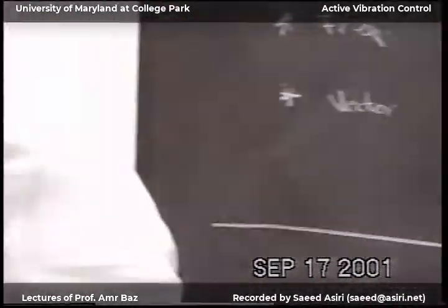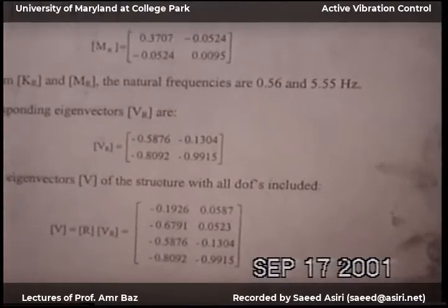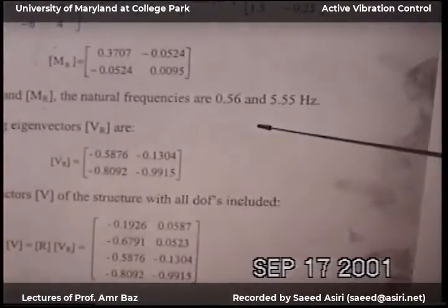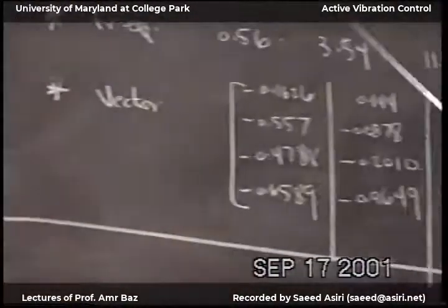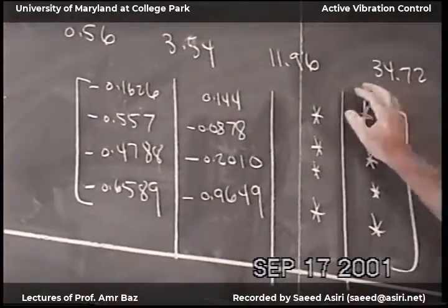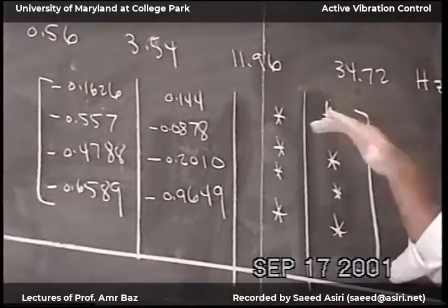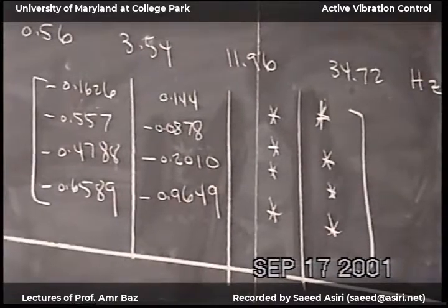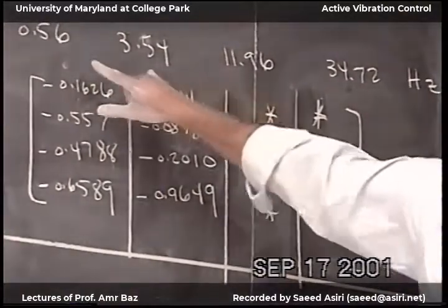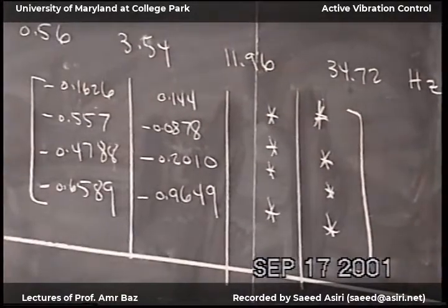Now let's look at the reduced order. The first frequency is 0.56, exactly like this. Okay? The second frequency is 5.5, and this is 3.5. And this is always expected. If I have this system, these two frequencies are correct. These two frequencies are very bad. If I make the structure 3 elements, the only thing that will coincide and match are the first two. These two will be way off. Because I'm simplifying the system, the high frequencies are bad.